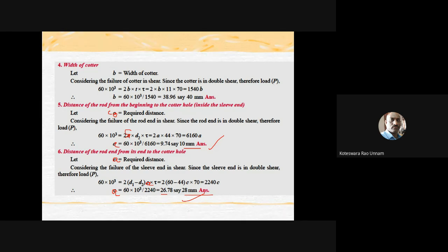So you need to draw the joint and show the dimensions also. For that, you don't need to remember the joint, it is already there in the data book. Take the figure from the data book, and using it you can draw the joint and represent all these dimensions. Therefore, you need to take empirical relations to find these two, capital L and small l.